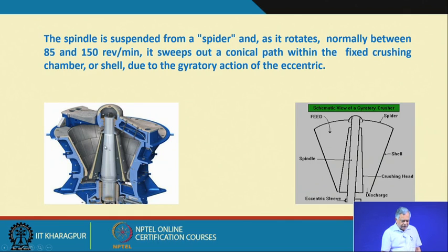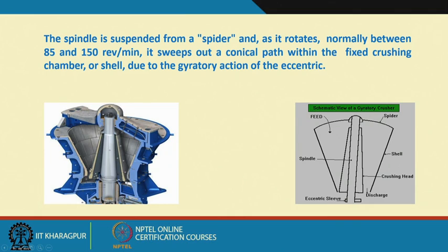So, they are again witnessing huge compressive forces, and the ores are progressively broken, and then this is the discharge, and the material which is already finer than this goes out. So, this is a continuous machine, because there is no swinging jaw here.